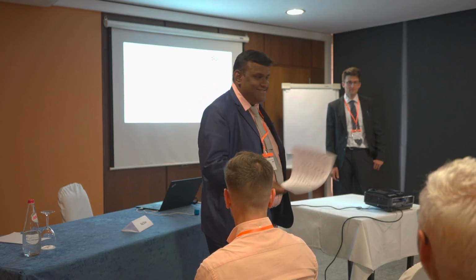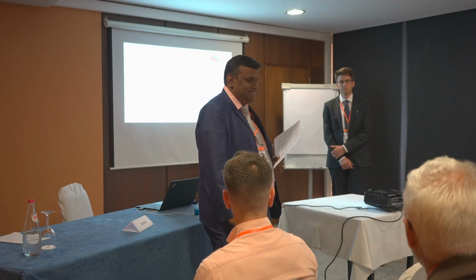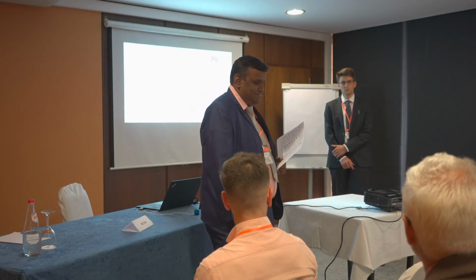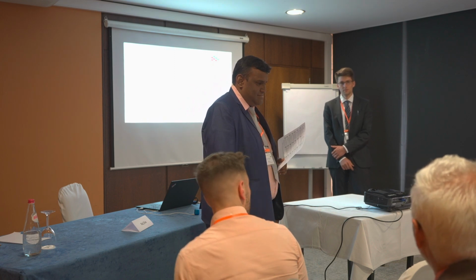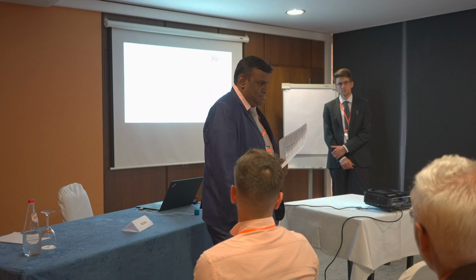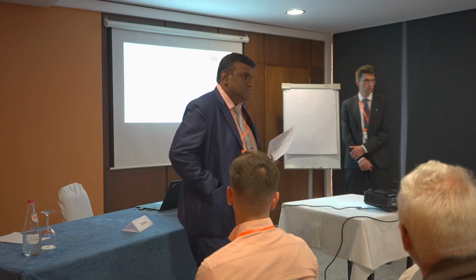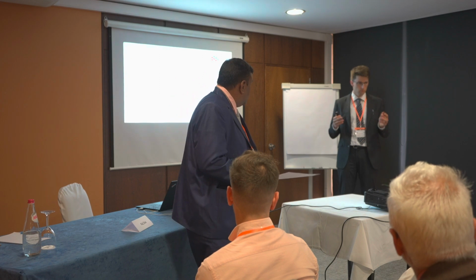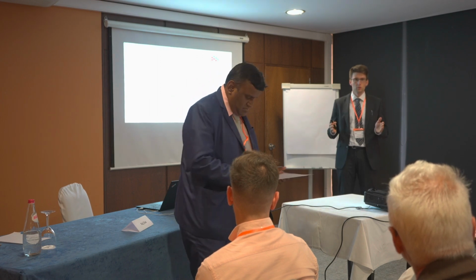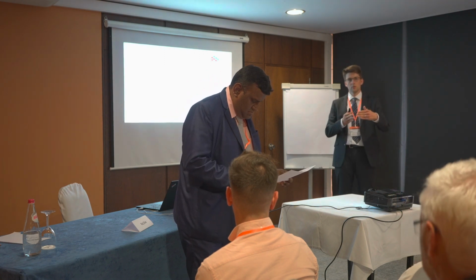Yes, I have a question. You use your optical extensometer for the calibration, and my question is, how do you calibrate this extensometer, and do you use a dynamic calibration or a static one? The only thing is to put the extensometer in the right position, so that there is a right angle between the bars and the extensometer.